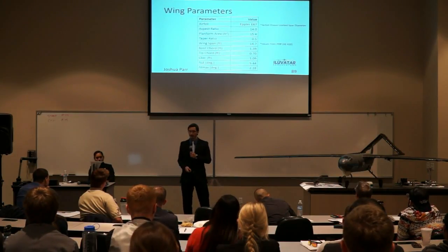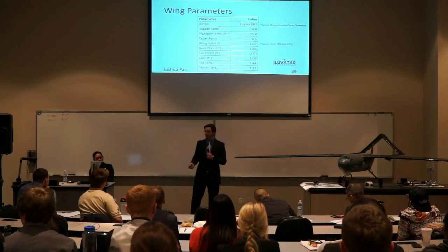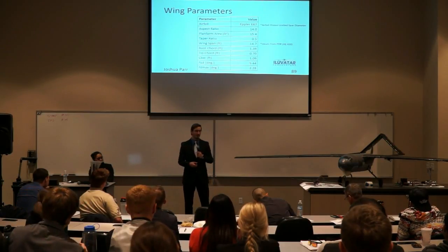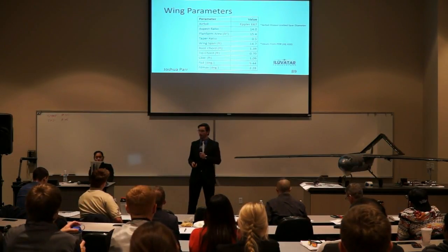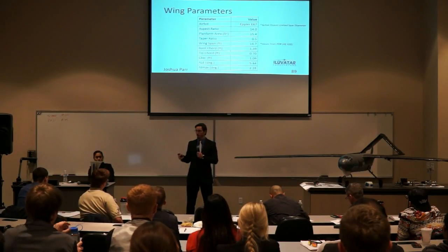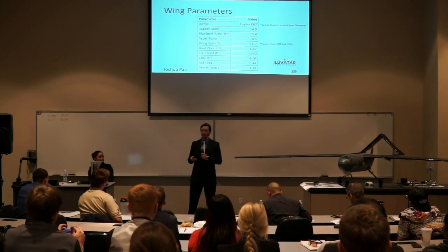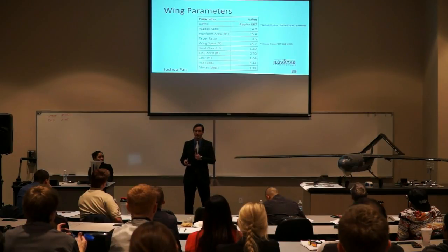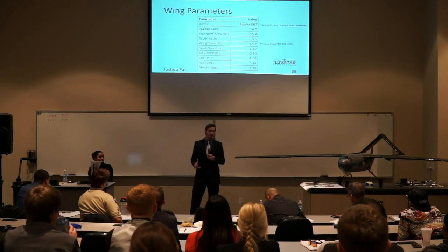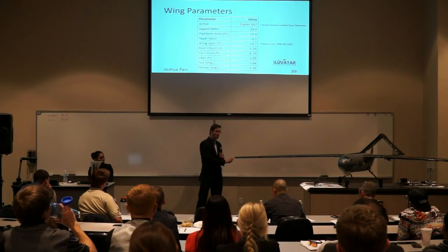So to start off, we have this massive wing here that's 14.7 feet. We use an Eppler E67 airfoil, which is actually a relatively thin airfoil. Then we have a root chord of 1.39 feet, and you couple that with a taper ratio of 0.5, you get a tip chord of 0.7. So you have this long wing, small tip chord, small aileron.